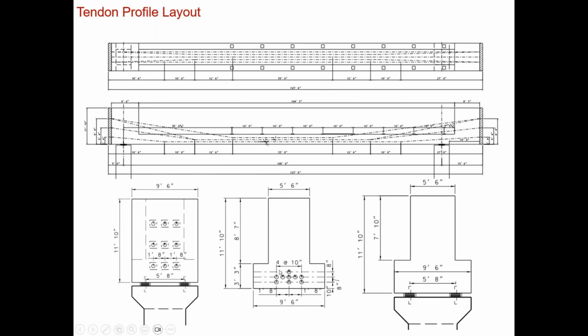and come up with the area of the tendons that's required. Then you can decide on the size of the tendon, like 19 strands or 20 strands or 27 strands or whatever, and you can decide what area of the tendon is going to be and the total area that is required, and this is how you can come up with the number of tendons that you need to apply in this bend. And then you can work out your way for the profile of the tendons.